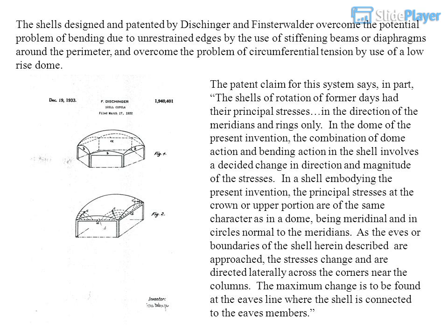In the dome of the present invention, the combination of dome action and bending action in the shell involves a decided change in direction and magnitude of the stresses. In a shell embodying the present invention, the principal stresses at the crown or upper portion are of the same character as in a dome, being meridional and in circles normal to the meridians.